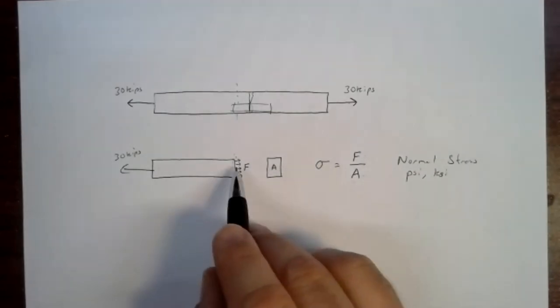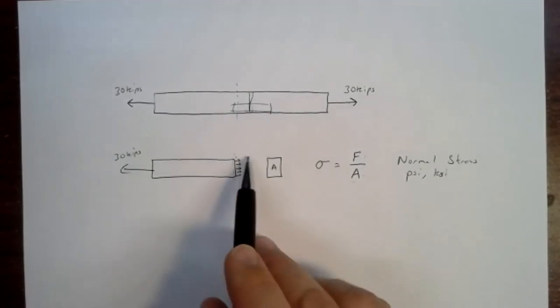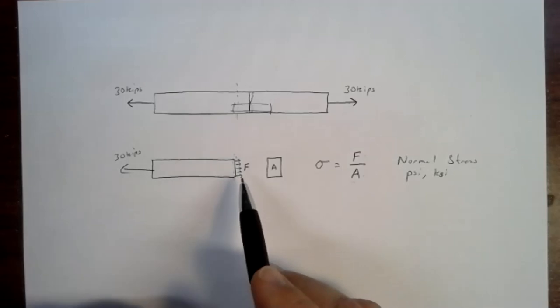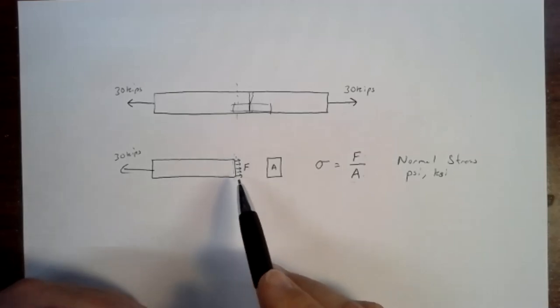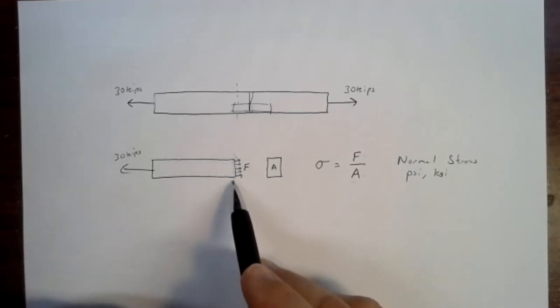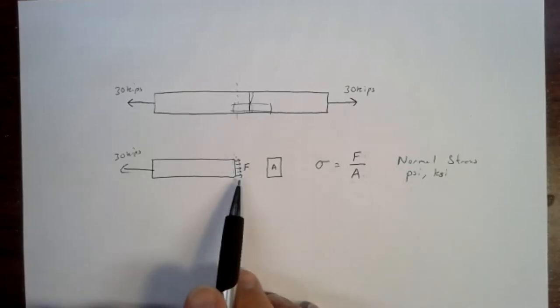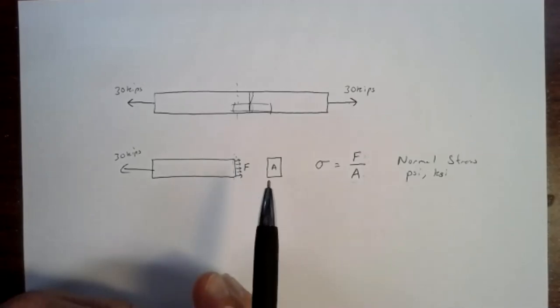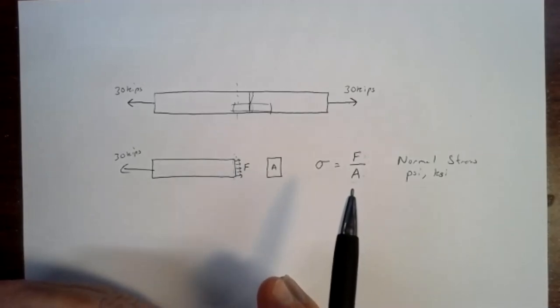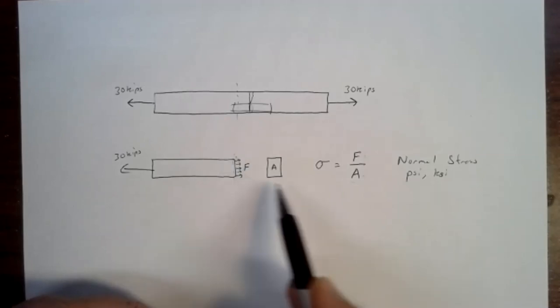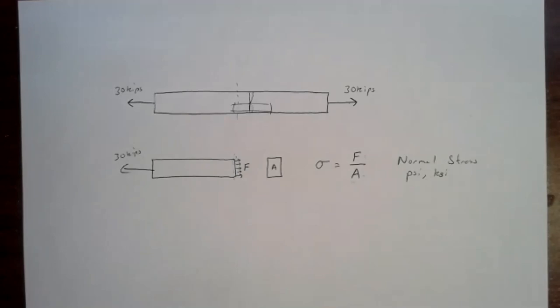Stress causes the bonds in between the molecules that make up the material and the grains that make up the material to change shape. Each inch of material deforms a little bit under stress. Now, if that's a tensile stress, then the material expands a little bit. If it's a compressive stress, where the force arrows here are pushing in instead of pushing out, then the material shrinks a little bit.